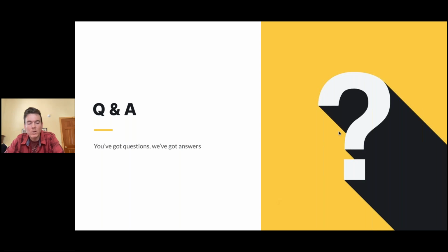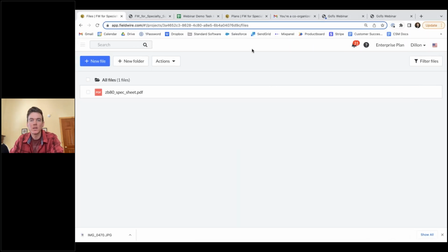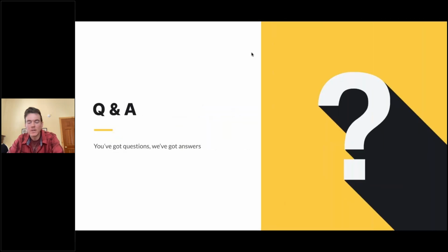Yeah, so the X and Y coordinate locations can be useful. You'll have to pull those out previously and get the exact locations. I can show you what that looks like, but I actually don't have that pulled up. I've found it's often more useful to just import them onto the plan and then drag and drop into the exact locations, because it can be a bit cumbersome to get all those X and Y coordinates entered within the task importer. We'll be sure to have somebody follow up with you on that and give you a demonstration on how to export those XY coordinates and re-import those.